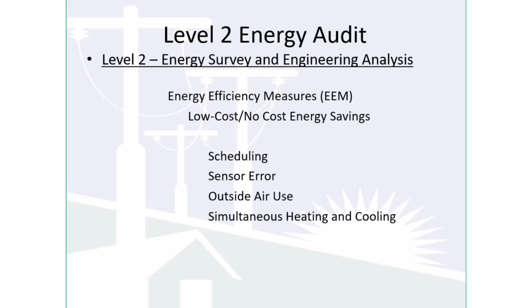If the building interior needs cooling and the outside air conditions are appropriate to do so, then the system is designed to introduce outside air for cooling and not do mechanical cooling. Both of these applications for the use of outside air are engineered to be precise. We don't want too much outside air coming into our facility. If too much outside air is coming in, say in the wintertime, then I have to heat that air up. And of course, in the summertime, I have to cool it down. So outside air needs to be controlled very precisely.